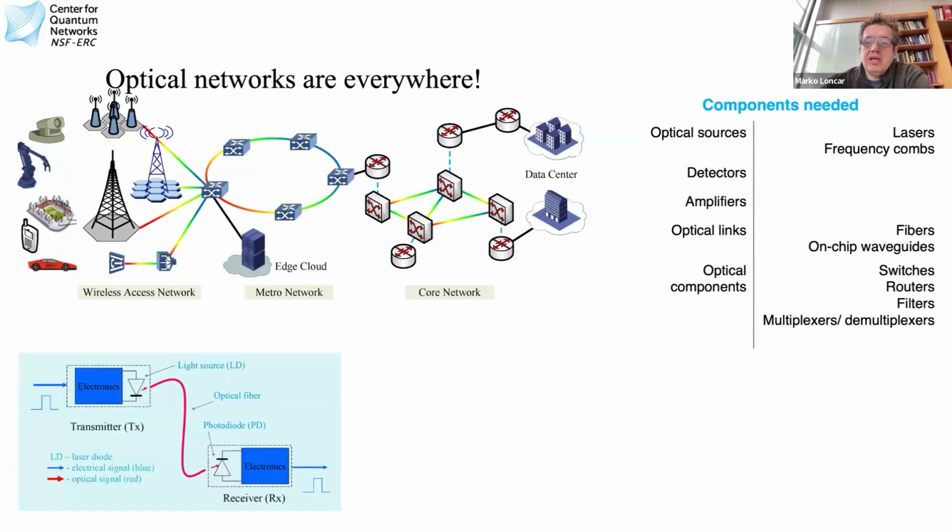The simplest way to think about this optical communication channel, this optical link, is the following. You have some sort of electronic computer, some information that sits in the electronics domain, because almost all of our computers today are at least electronics based. In order to send information via an optical carrier, you need to turn, for example, a light emitting diode on and off as the bits of ones and zeros come that you want to transmit. You have a bit stream of ones and zeros. You can turn the diode on and off, and that sends an optical bit stream.